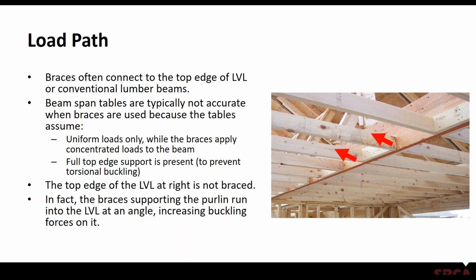They're helping to brace the top of that beam, but they're also applying roof load to the top of that beam. And chances are, if this beam was sized, the sizing software that was used, you want to make sure that it tells you what the maximum unbraced length of that beam is or can be for the loads applied to it, to make sure that it's not assuming that that top edge of that beam is laterally restrained along its entire length, because this one is not.